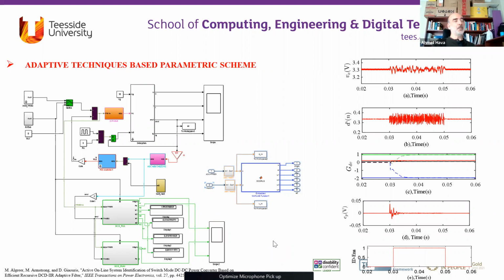But the other thing, in my experience with power converters, is that yes, load variation is important and it can be as steep as shown here. But the source side can also be problematic. For example, it could include some small disturbance, some periodic or aperiodic signals, and those disturbances could affect the output in some strict regulation applications. The other is in the circuit itself: the inductor especially can be nonlinear, in the sense that it could be made of material and structure such that it's cost-effective, and that boils down to a highly nonlinear inductor, where as the current goes from half to full rated, the inductance can change by a large amount.